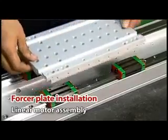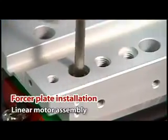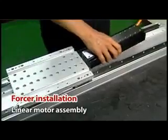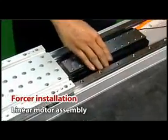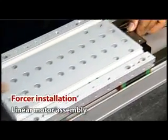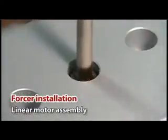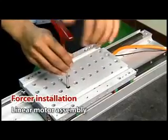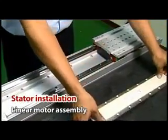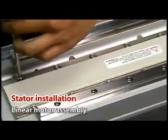Forcer plate installation. The forcer plate serves to connect the forcer and blocks and helps the forcer disperse heat. Forcer installation. Joining the forcer and forcer plate. To prevent mutual attraction, special care must be taken to avoid letting the forcer get too close to the stator during installation. Stator installation. Because the stator possesses great magnetic strength, care must be taken to maintain safety during installation.